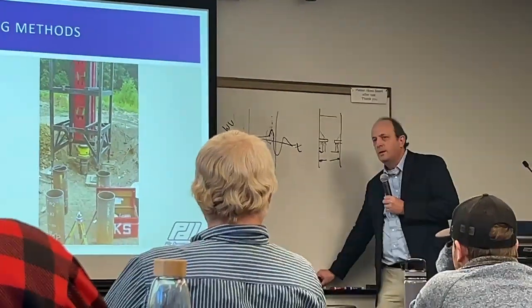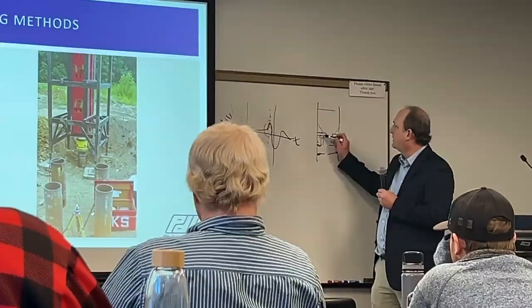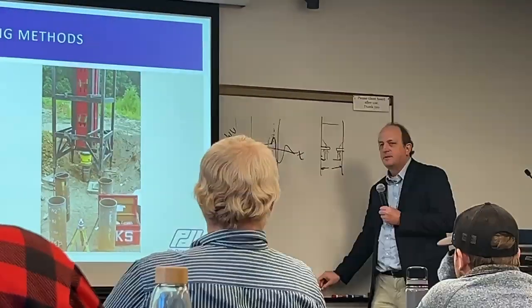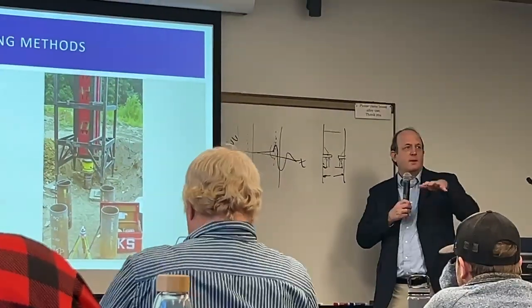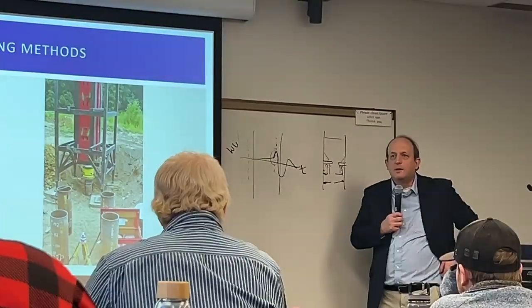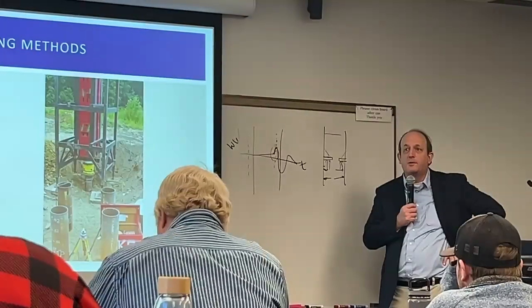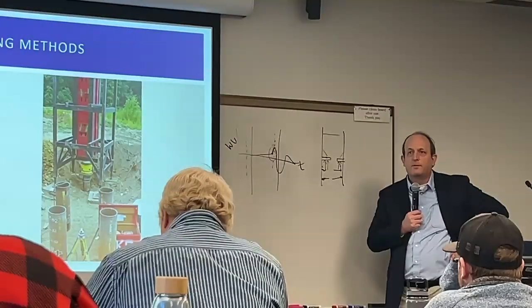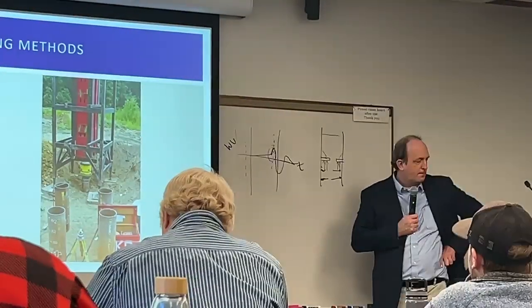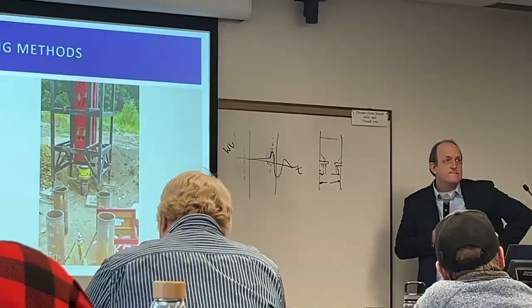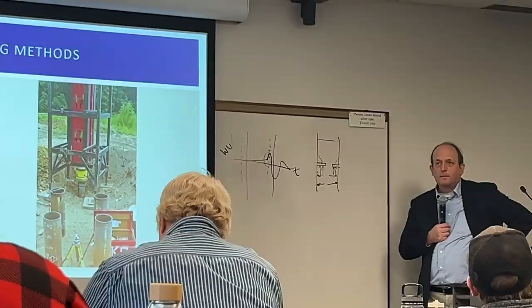But oftentimes what we think happens is stuff gets trapped in there and behaves more like a mattress than the hard end bearing result from a gravel layer that you thought you were going to get, or from rock or from something else. We had a project in southern Illinois where we cut them out after the first couple piles, because the drive times took forever.